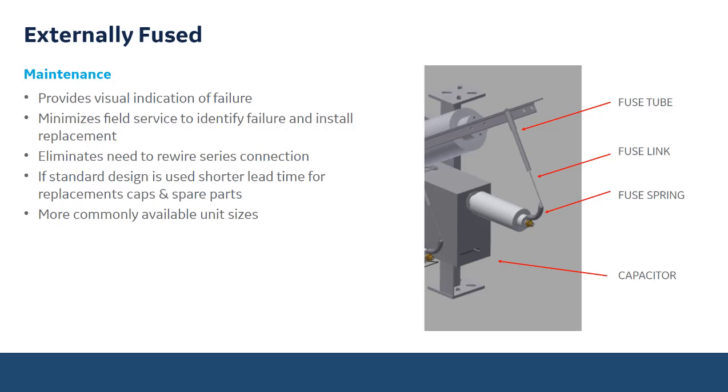Also, the externally fused, if the standard unit design is used, a shorter lead time for the replacement caps and spare parts are available, and most commonly available unit sizes are for the externally fused. And so you see, there's a lot of benefits of ordering a standardized system if you can.